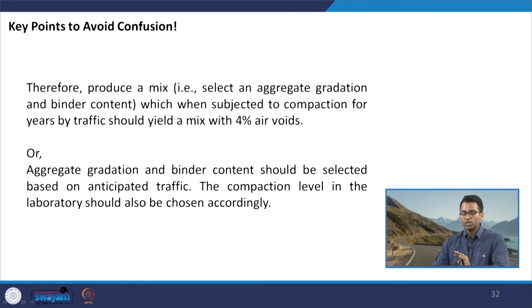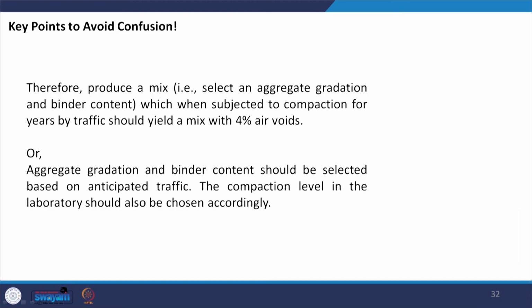When I say produce a mix, it means that we have to select an aggregate gradation and the appropriate binder content, which when subjected to compaction, it makes the mix itself project dependent, that is, for which project, for which anticipated traffic I am going to prepare this mixture. So, which when subjected to compaction for years by traffic should yield a mix with 4% air void.